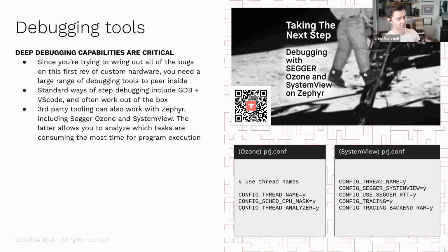I'm not sure how much of my video is available on screen, but as you start to put stuff into cases, you want to make sure that you have as much visibility under the hood now that you are closing things off. Dev boards are great because they break out all the pins, but then you start to enclose things in plastic, shrink things down. You're not going to have as much capability to probe different areas. And so you want to have other ways to do that sort of thing.